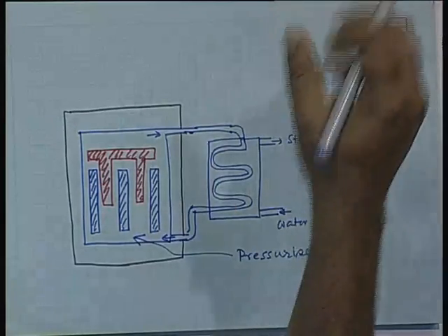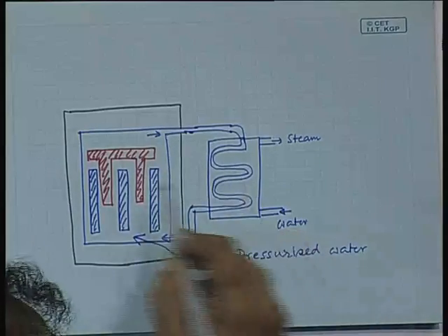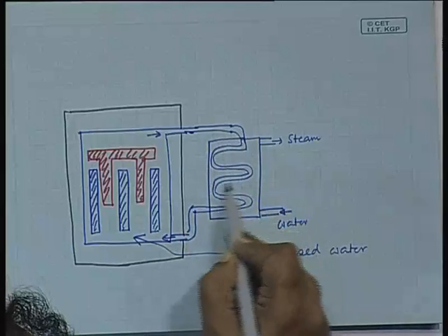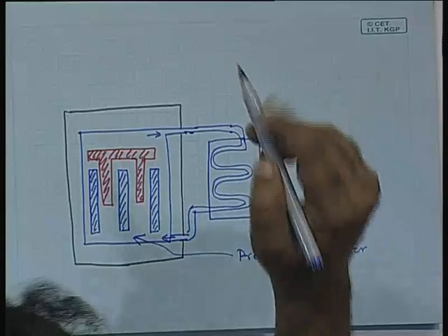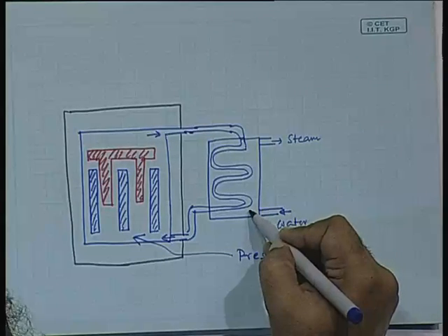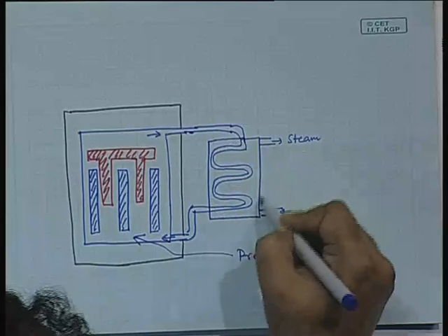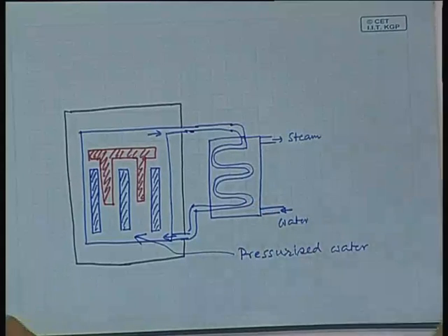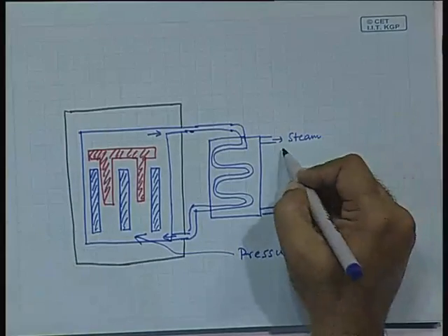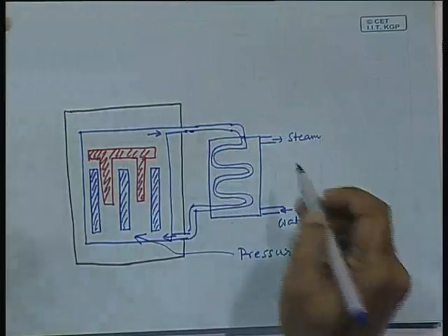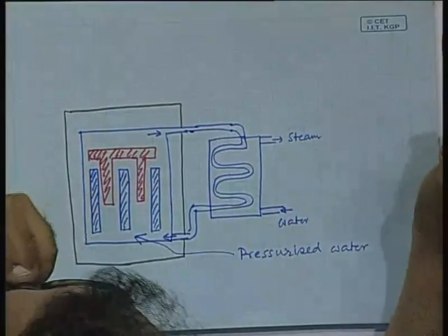Naturally it acts as a very good coolant, and then that passes through this. So, here is the water path, pressurized water path, and here you have the normal water coming after the condenser, taking the heat from this heat exchanger and going out as steam to the turbine. Of course, after that flushing stage, flushing means where you bring down the pressure a bit, so that it becomes superheated steam, then to the turbine.